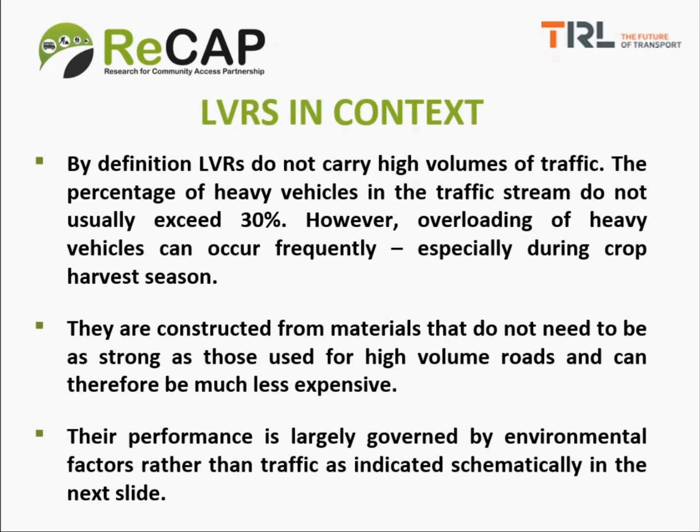So there's a risk of high levels of overloading, and there are risks of climate. And of course, the low volume roads are constructed from materials that do not need to be as strong as those used for the high volume roads, because we want them to be less expensive. Their performance is actually largely governed by the environmental factors, because, as I say, we're really hoping or expecting them not to carry too much heavy traffic.